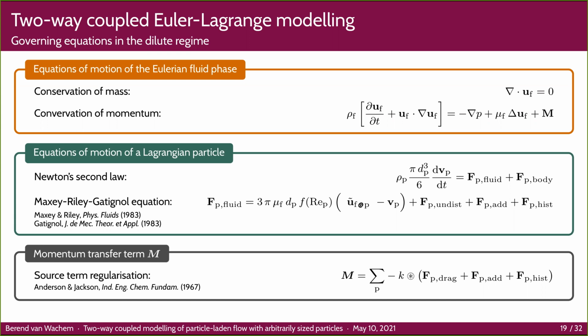Fortunately for gas solid fluidized beds, the force scales as the particle density over the fluid density, so it becomes small for gas particle flows. But as the fluid density increases and comes near particle density, that force becomes important. Okay, thanks. It's also called the Bassett force. Yeah, okay, that's indeed a term we also often use.